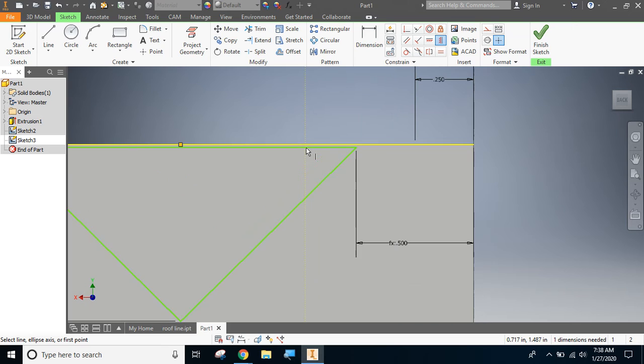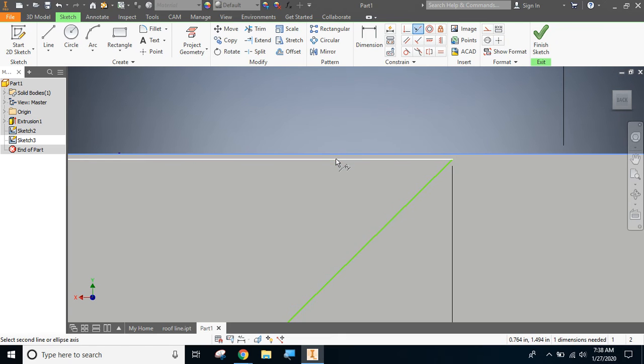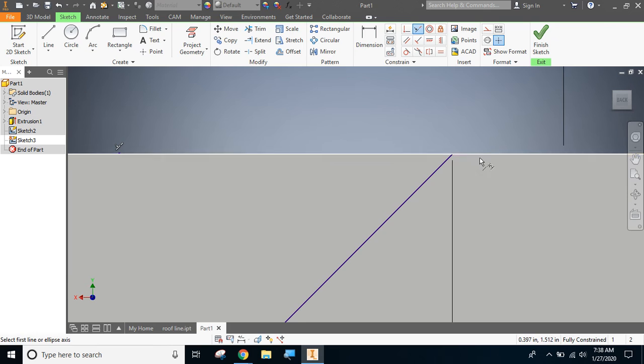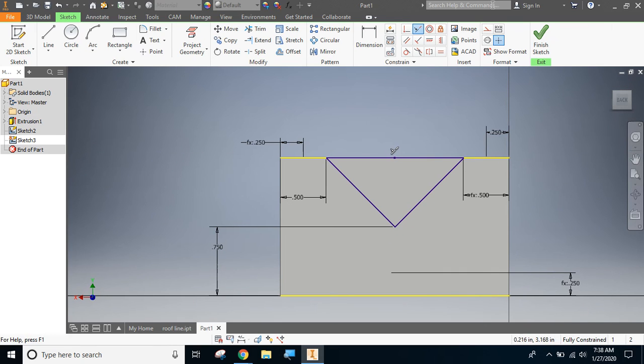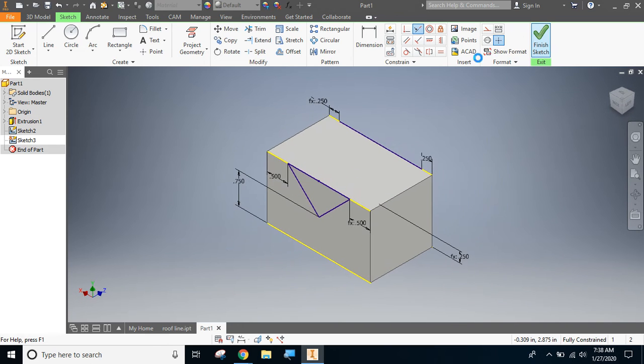The other thing I think happened here, oh, I didn't use my inferences very well. You can see I got a gap between the top of my object and the top of that line. So I'm going to use my collinear constraint to make these two lie on the same line. Right now I've got a fully constrained drawing. Right, and that's, again, that engineering thing. You got to check your drawings as you're making them. Make sure it looks correct versus the dimension drawings on my PLTW.